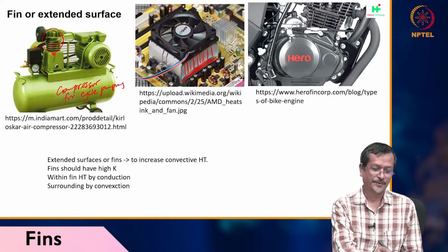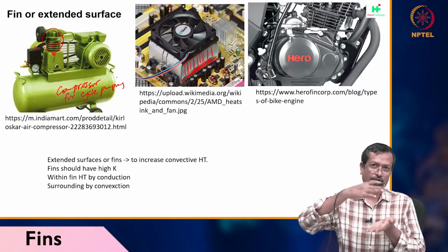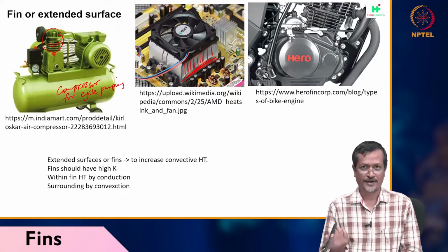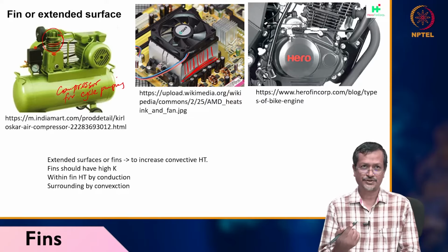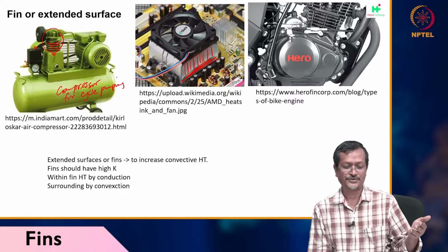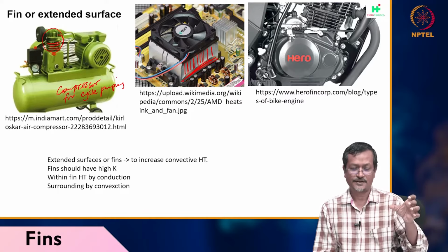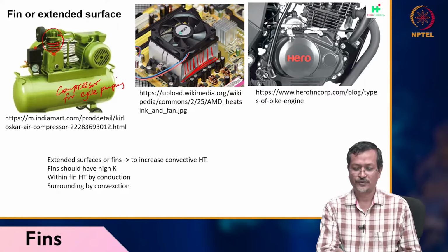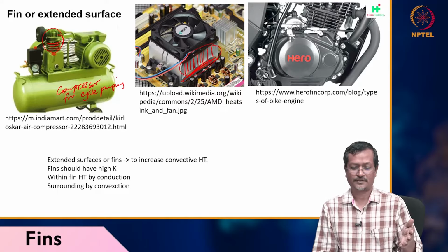There will be a piston cylinder arrangement, where air compression is happening. When air compression happens, the air temperature inside will be very high. If you reduce that high temperature, the system performance will increase. That is why these fins, or extended surfaces, will be there. Those extended surfaces reduce the temperature of the cylinder, so that whole system performance increases and electrical power consumption will be lower. In a computer also, if you do not reduce temperature, your circuitry can burn.